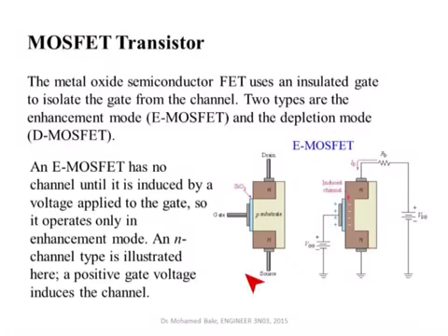So for example, let's take a look at this transistor here. This is a typical N-type E-MOSFET. So you have here two N-type electrodes. These are the drain and the source. And you have a P-type body or P-type substrate. This is an insulator, an SiO2 layer. And this is a metal electrode.